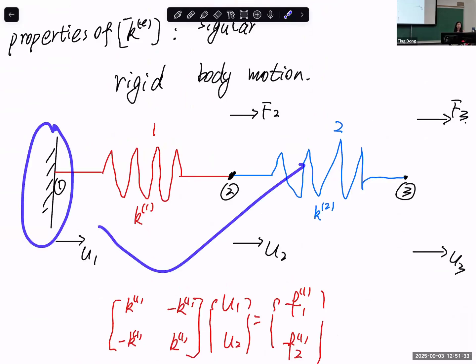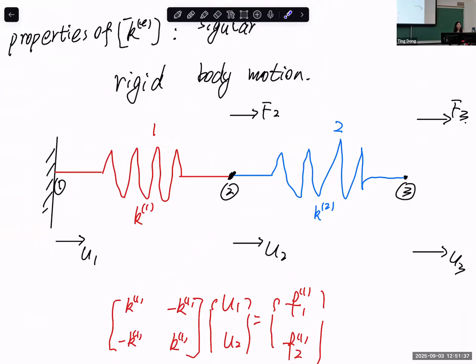F1 is a reaction force, and in FEA, reaction force is always an unknown force. I know some of you can see that this is F2, that's F3, and the reaction force should be F2 plus F3 in the negative. No, we don't do that. This is a simple situation, of course, this is the beginning of the semester. You can just look at it, the reaction force, based on what you learned from statics. But remember that in our FEA, when we get more complicated, you normally can't just see the problem and know what the reaction force is. So we just always assume that reaction forces are unknown forces.